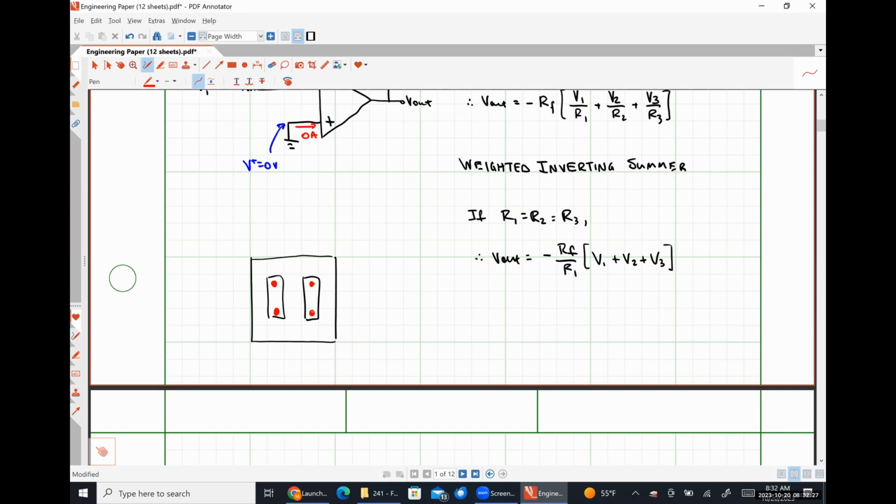So this is literally a direct application of an inverting summing amplifier, in a common commercial product like a digital bathroom scale. It takes all of those different strains and amplifies them by some factor that corresponds to your weight. So you could think of the output of the strain gauge as being probably millivolts per pound. Add those millivolts per pound together, scale it by the appropriate scaling factor established by the resistors to make the math work out, and boom, your weight shows up as the digital output.